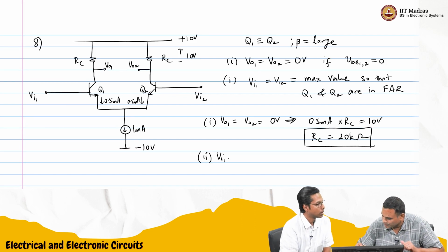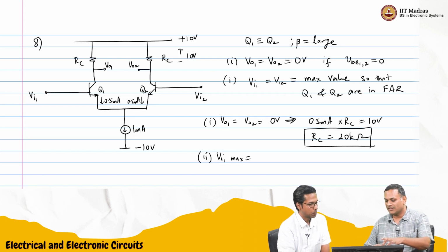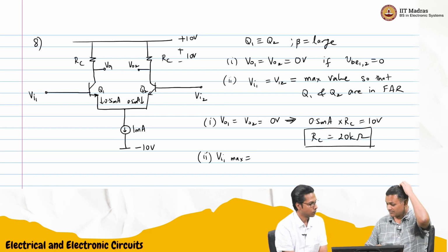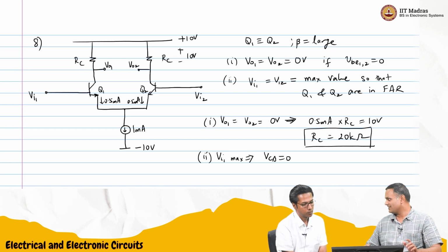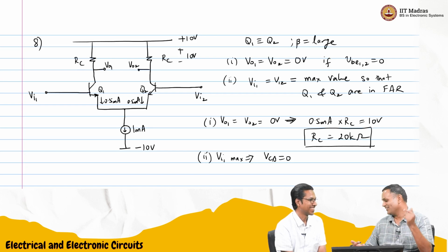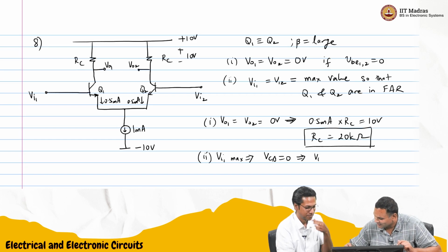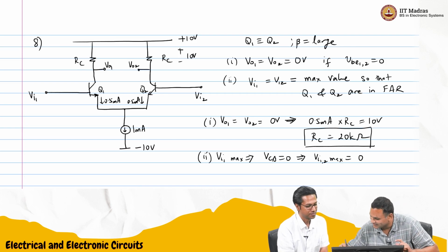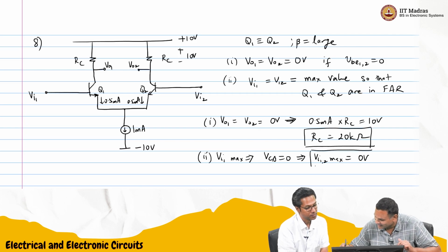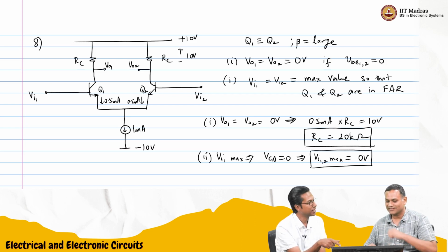At this maximum, the collector base junction is zero biased, so VCB is 0. We know VC. Now the solution is easy once you recognize this. The maximum is just 0 volts. Again, one step, but important to recognize what is happening in the circuit. Nice question. So this means I cannot give any positive signal.